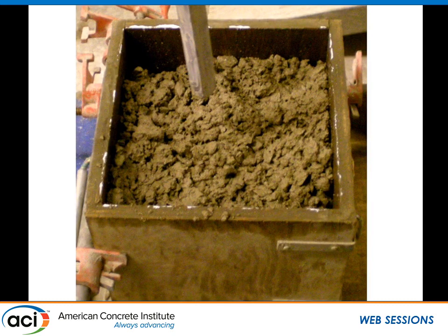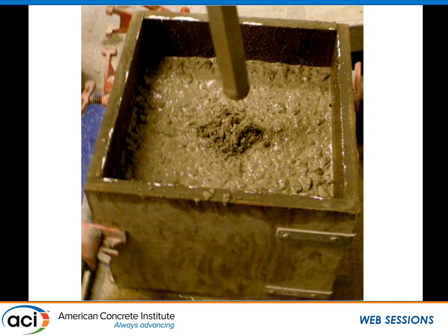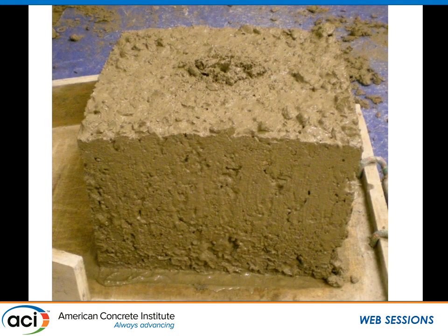Looks similar. Vibrator goes in, sucker flows like water. It's amazing. It's amazing. Drop the edges off. It's beautiful. Look at the sides. No voids. Why are there no voids? Because it consolidated. Because the vibrator worked. Because it responded to vibration. Okay? And this is what you want. A concrete brownie.